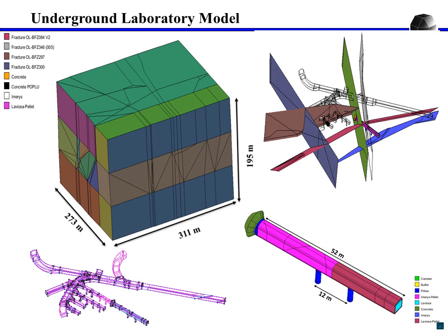The vertical boreholes are intended for installing not directly nuclear waste, but heaters that simulate the nuclear waste, and then all the thermo, hydro, and mechanical processes can be investigated in situ. Measurements are made, and the models that can predict the evolution of, as I said, temperature, pressures, displacements, stresses, etc.